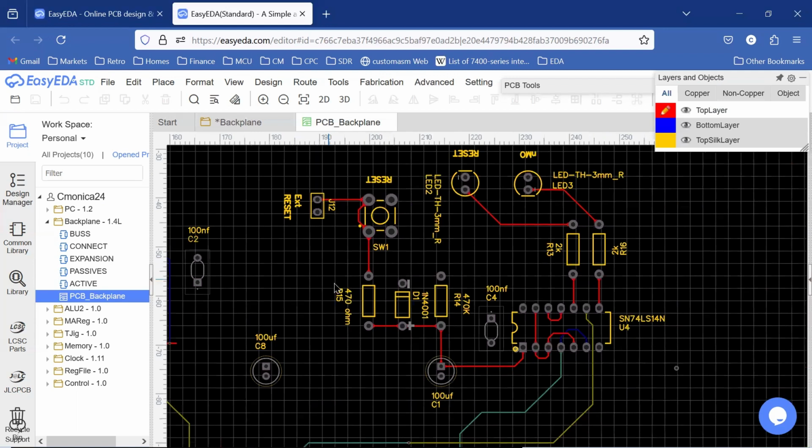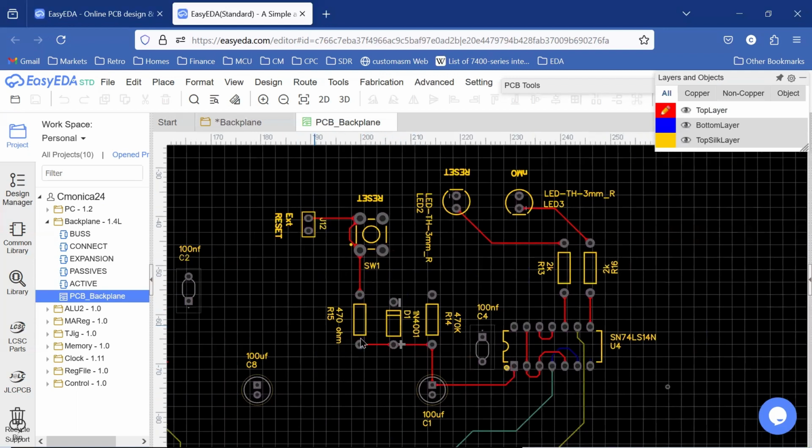And then over here we have our reset circuit, right? Here's our 74LS14, our Schmitt inverter, that we're using. Here's our reset switch, and here's our reset LED, right? That's being driven from the inverter. And now I've also brought out an additional header here that will allow us to have that external reset button or switch on our enclosure once we build an enclosure.